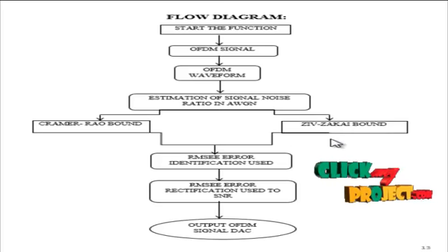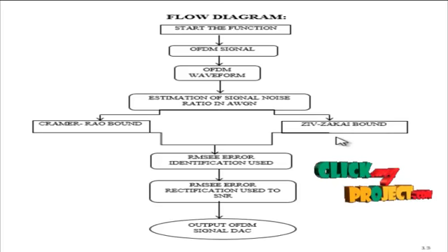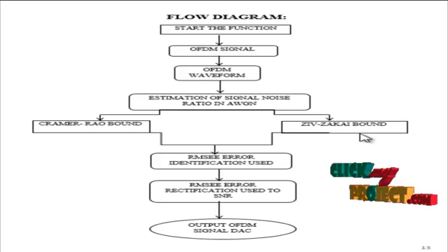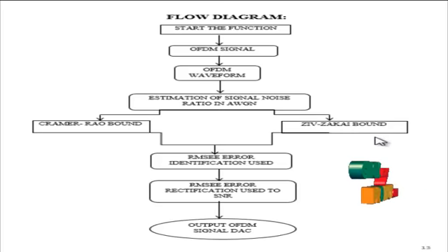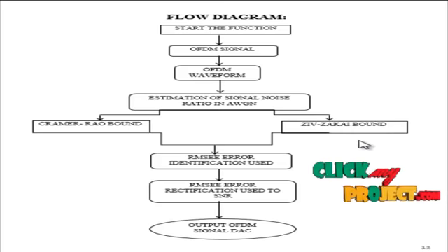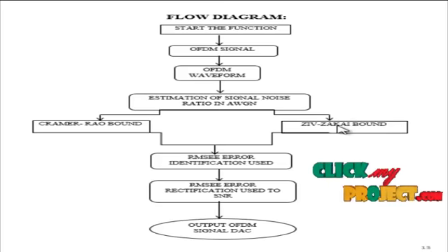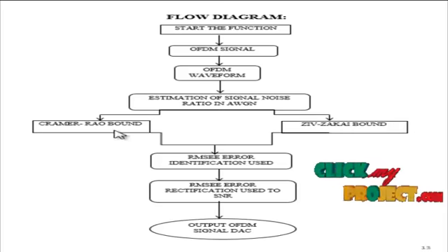TOA RMSE behavior is explored not only in the asymptotic region but also in the threshold region by introducing a novel quantity which is complementary to the widely adopted Gabor bandwidth. Finally, the trade-off between asymptotic and threshold performance is identified, showing that the GB is not the only parameter to consider for designing a TOA reference signal.